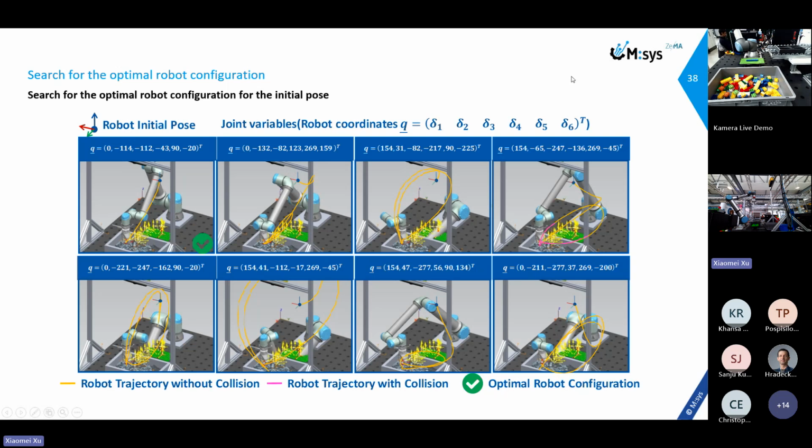When all the robot parts related to the TCP are determined, the configuration planner focuses on the robot configuration. Here is an example of how the robot configuration will be planned from an initial pose to the first waypoint. With the backwards kinematics, we can find a maximum of A robot configurations. I compare the sum of the joint variable change across A robot configurations. I take the configuration with the minimal joint variable change as my robot configuration and proceed with the planning.